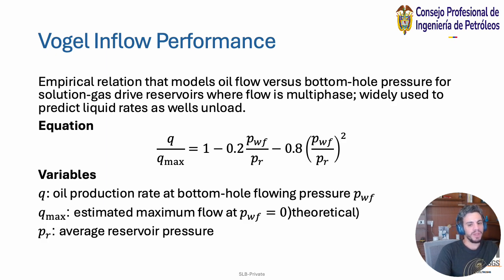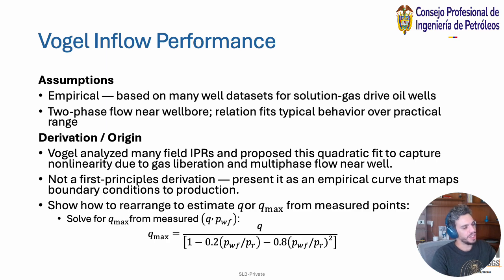I apologize. But why is this needed? Basically, Darcy's law does not hold directly once you enter the multi-phase world, right? And the multi-phase effects are what dominate near the wellbore. So what this equation is trying to provide is a curve describing the relationship between pressure and flow in a more realistic sense, right? So again, let's go through our assumptions.